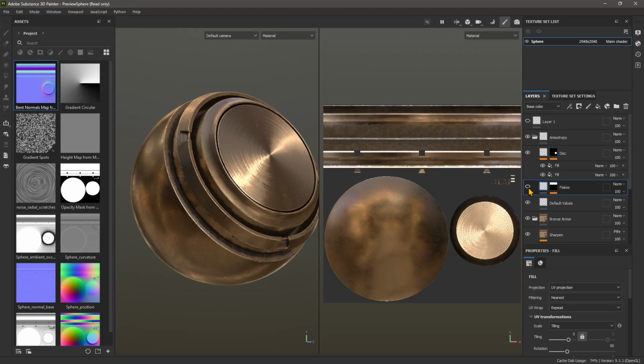Now you can turn that off if you don't want it, or you can just compare by turning that on and off. But this is a tileable texture. So to show you that, we can use this gizmo here that is called a manipulator. And you can hide and show the manipulator, and you can make it with smaller grips or larger grips, which are these little squares. So if you click on those squares, you can make this move around. Well, now we're actually resizing. So we're making this bigger and bigger.